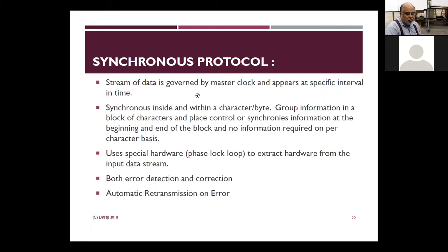When you send the clock, the data speed can be very high, because the clock makes sure that every data bit is clocked in on the other end at the right time. Since the transmitter is also sending the clock, the receiver has no problem; it can receive data automatically with the clock.